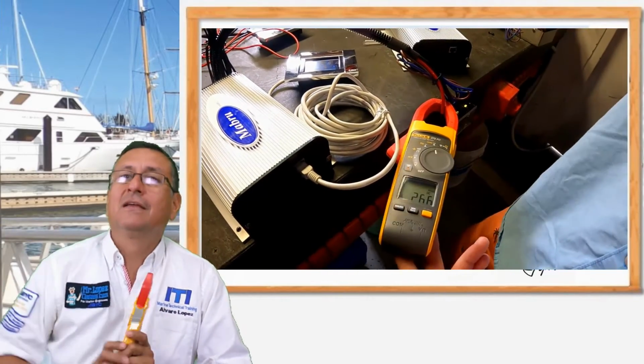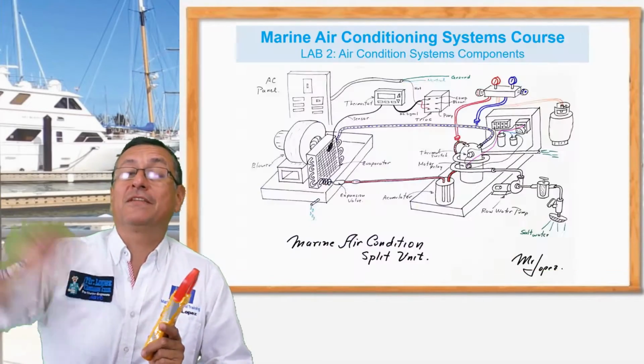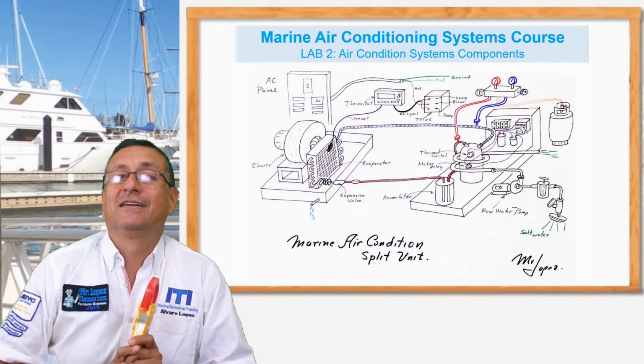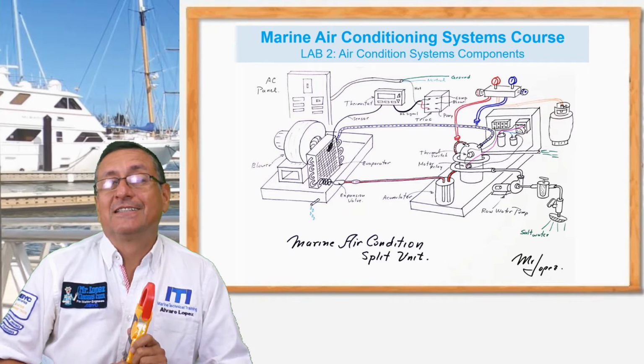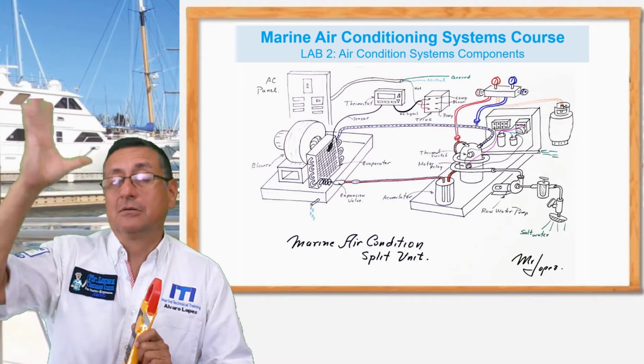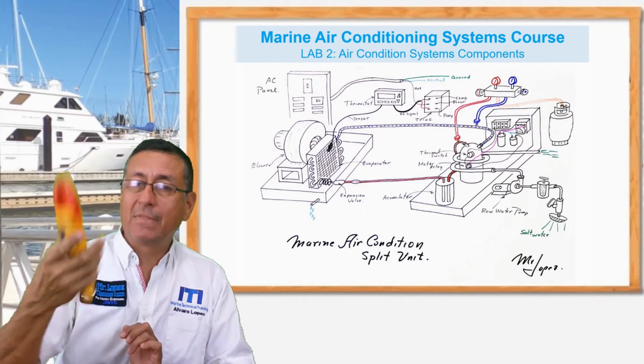And you copy. That reading should be according with the capacity of the breaker, the main breaker. If that reading is superior, it's not good because the breaker opens. You like it? This is with the clamp.